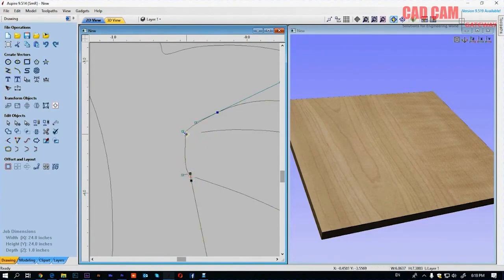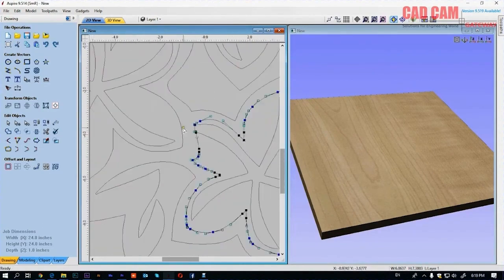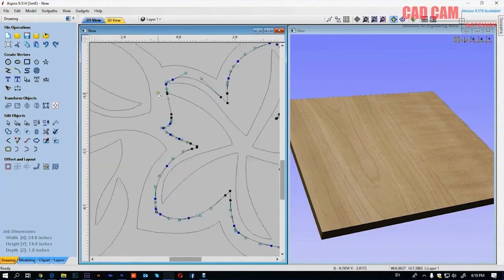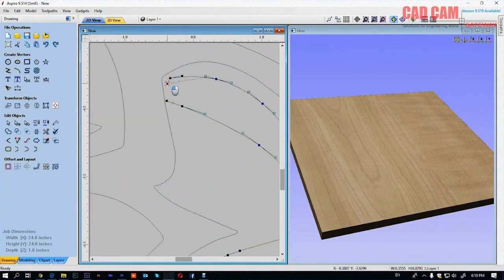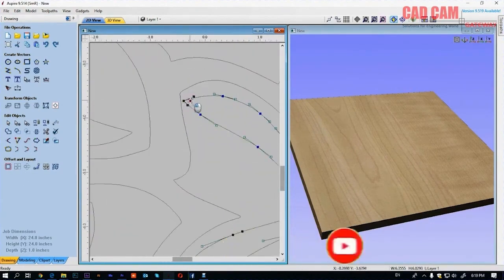Okay, so now the lines we have, we can join them together. From here, I delete the point. So viewers, this shape is now in front of you. Here you can smooth it as you wish. See, everything is under your control. And these 2 points that we just freed, you can also close them together. Right-click and select both of them, and you have the option to join curves. I joined the curves, and with the Node tool, take them to smooth point so that smoothness is added. I smoothed it a little. From here, you can also move this object slightly backward, move it back a bit.